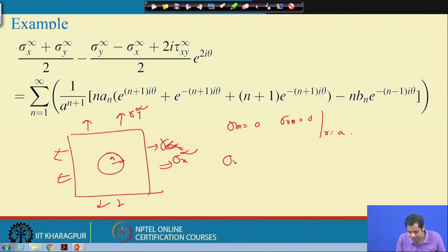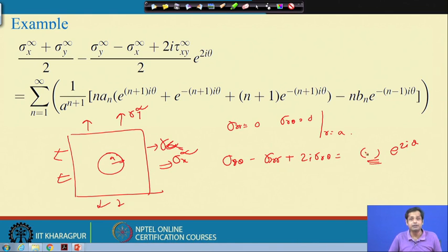Now you have an expression of sigma theta theta minus sigma rr plus 2i sigma r theta equal to something into e to the 2i theta, and this something is written in terms of the potential gamma z and psi z. This part is 0 at this boundary. If you satisfy this equation at this boundary, and substitute the expression of the potential we just discussed, then you slightly rearrange it and get this expression.